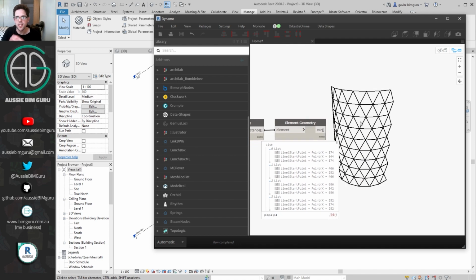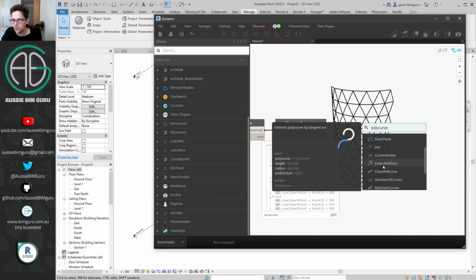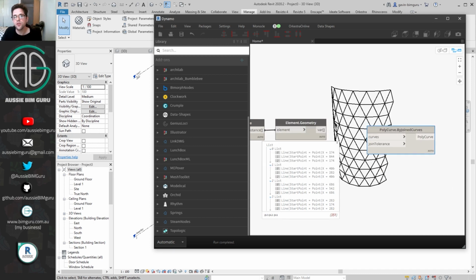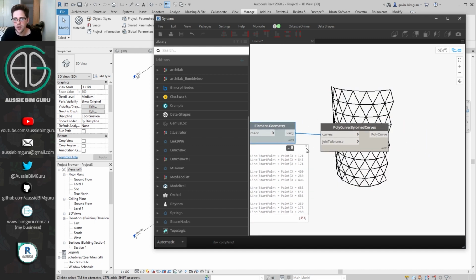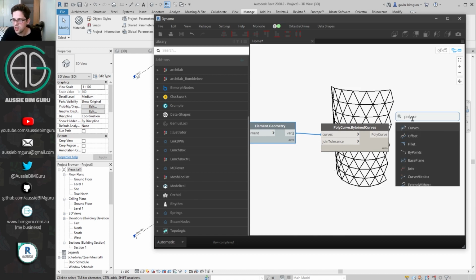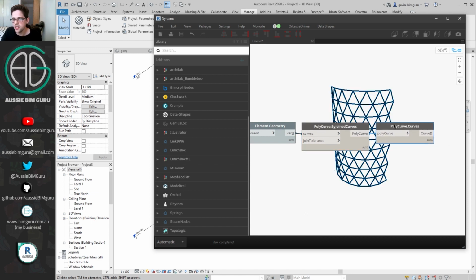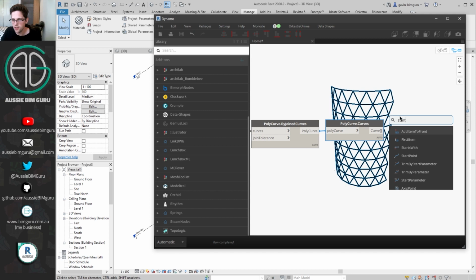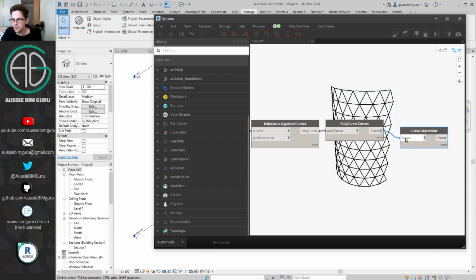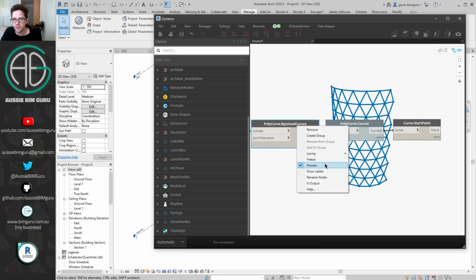Now these may not be in an order going around the panel in a clockwise or anti-clockwise fashion. I'm going to turn these into polycurves because joining curves into polycurves forces them into a circular order. But then I'm just going to take those curves back out of the polycurve once it's created. This is a little handy trick you can use to reorder curves into a logical order. And now the curves should be in a logical order, and we can now take the start point of each of those. So now we get the 3 points that represent each of those panels essentially.